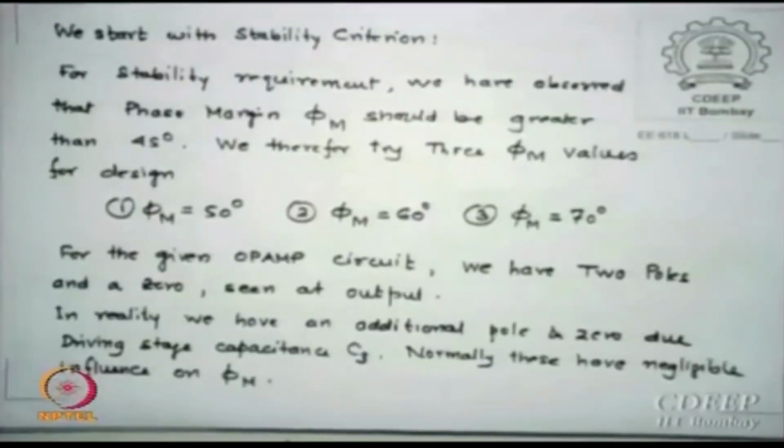The first thing my worry is always for any amplifier is how stable it will be. And this morning I said with great fanfare that as long as your phase margin is 45 degrees and up to 70 degrees, we believe the op-amp or amplifier will remain stable. And I have explained enough this morning what anything lower or higher can create.